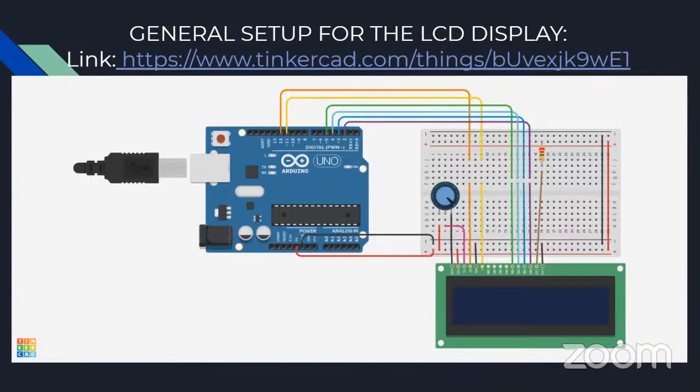But using Arduino directly, that would take a lot of time and a lot of low-level coding that is not necessary for us, because it would require us to understand the intricate workings of an LCD and the circuit inside it. So we were just going to show you the connections, and there are libraries in Arduino that already include all of this low-level programming as nice little functions, like set cursor or a print function. Then we can just type in what we want to write and it will print it on the LCD.